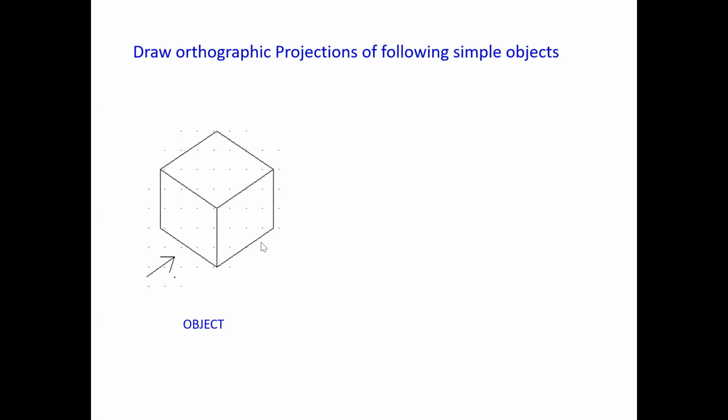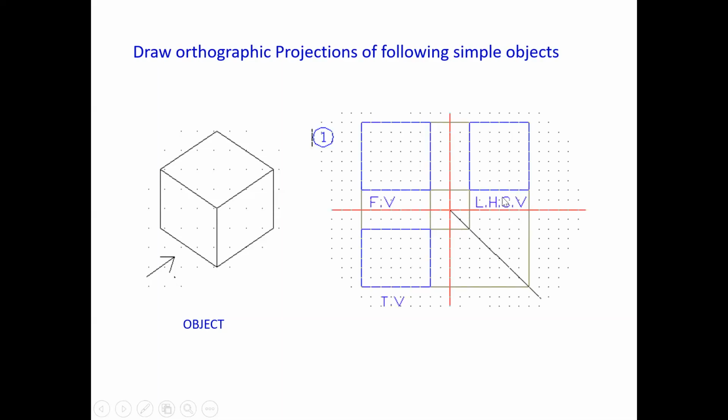So here you will get the right hand side view. It is always at the left side. Purposefully I have shown it here. Wrong answer. Here it is the left hand side, so this is a wrong answer. Getting? So the front view should be on this side and the right hand side view on this side. The correct answer is there and the top view is here. So this is the wrong answer. In examination, if you draw like this, then the marks will be cut, probably half of the marks.